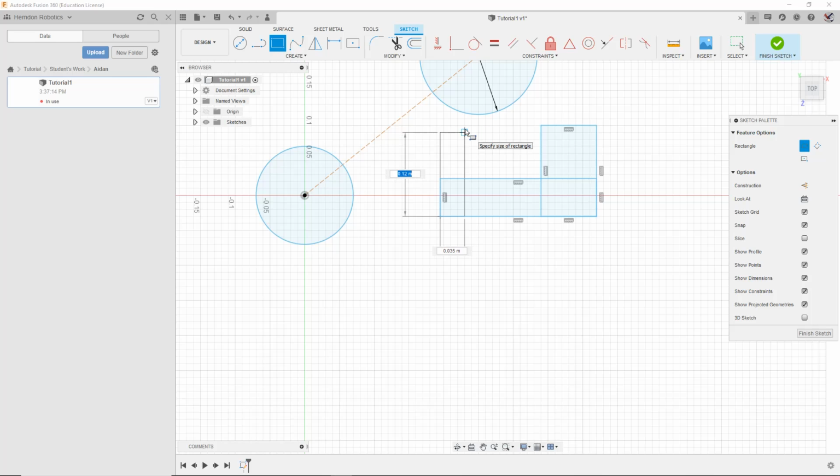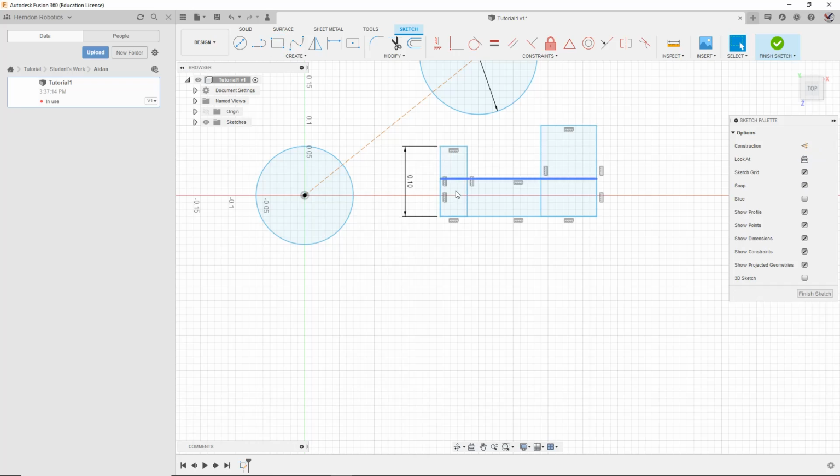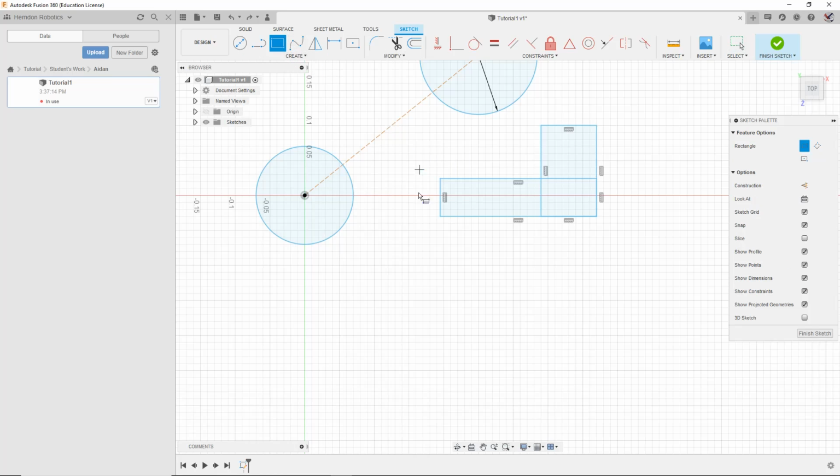And you can change these measurements like I said. So I can hit tab and go in between them, 0.11. And what the default for this normally is, it takes up the default for whatever you're currently working on. So obviously it's set to meters right now, so it's going to stay in meters. However, if I go to 11, I type a space, I can type inches, it's now 11 inches. So that lets me modify in some pretty cool ways. I can type feet, I can type yard. It just allows me to edit it.